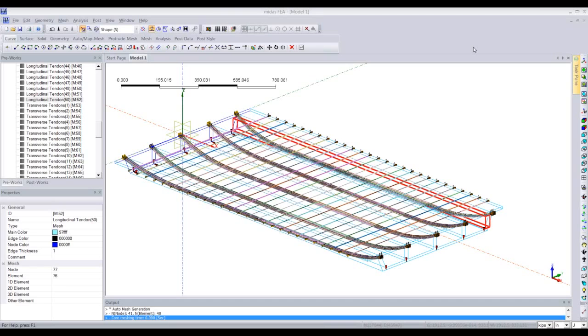There is one question by Mr. Ramin. The question is, why the second load case? Generally, we do not require the transverse load case because the first load case would have the transverse results in it. So we don't need it, but I was just telling you that you can define more than one analysis case in Midas FEA, and you can analyze them individually to obtain the results.